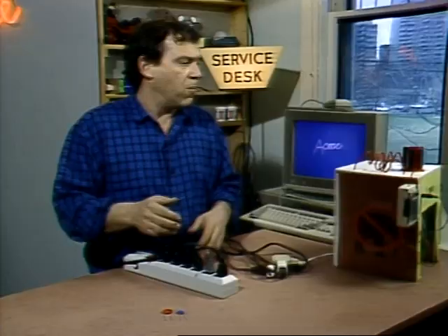Very nice, and the purveyors of paranoia will convince you that this happens all too often, and that not having their product will ensure routine loss of data or immediate destruction, whichever you're prepared to believe. Gee whiz, the MOVs are good things, but they only cost a couple of bucks at the electronics store. In an outlet strip or a multiple outlet thing, they cost up to $50 more. The untold side of the surge story is that most electronic equipment has to be designed to withstand the aforementioned surges anyway. And they do this with built-in MOVs, line filters, and a lot of other safety-related components.